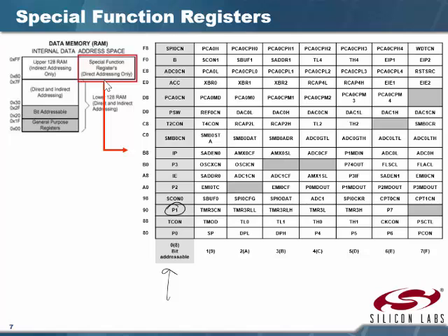As we look at some of these, these are bit addressables. These are not. This column here is bit addressable, everything in this gray one. So P1. I can look at P1.1, for example, and that's bit 1 of P1. I can look at P1.0. I can look at individual bits. Right here, P2. Each one of these. This is our timer control. Now we also have along here, these are also special function registers.